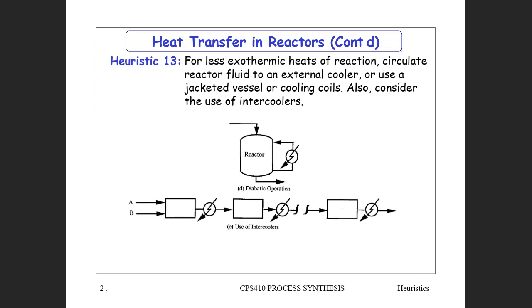This, of course, is a very good way of scaling up, because if this were a CSTR, you would have an equal temperature all the way through this reactor, and so whatever you do in the laboratory will be totally mimicked in your plant. You can operate this and control it at exactly the right temperature very nicely.